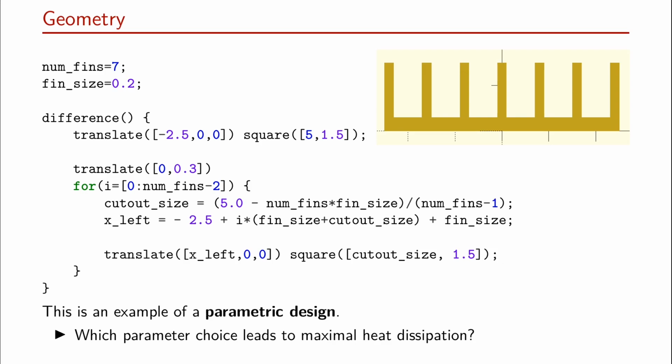And if we have a parametric design, then we can very easily use that parametric design in order to generate different meshes, run different simulations, compare the results, and see which parameters need to be varied in order to improve the result, or even to just figure out which parameters have a big influence on the final temperature distribution that we want to look at.